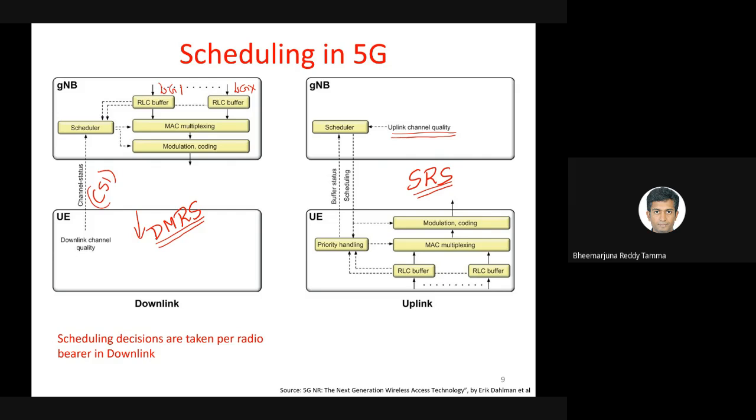Look at what is happening in uplink. In the case of uplink, make a note that even though it is the users who want to send the data in uplink, who should be transmitting at what time is all controlled by the base station. That way, both the downlink scheduling and uplink scheduling are running inside the base station itself. Basically, it's kind of a remote control that we are exercising at the base station in the context of uplink